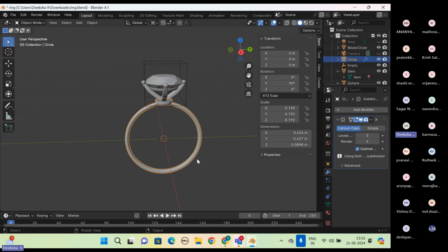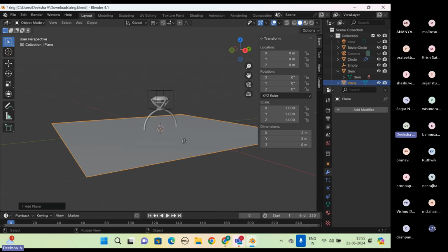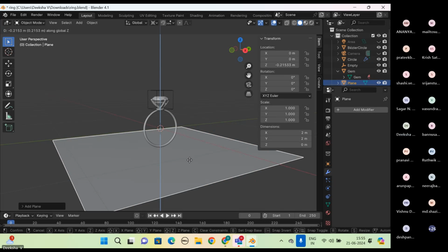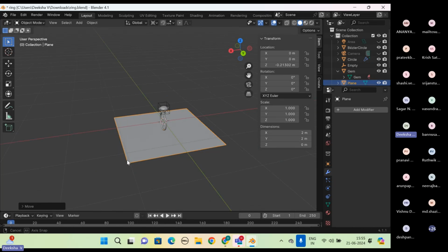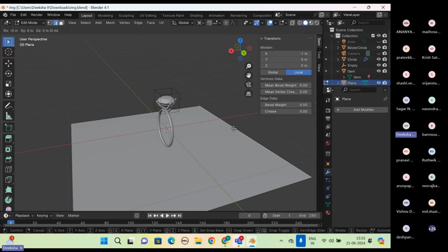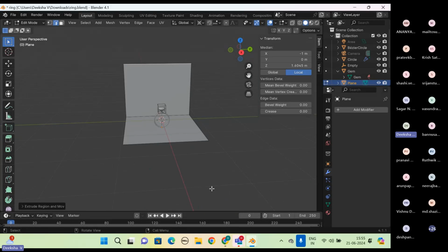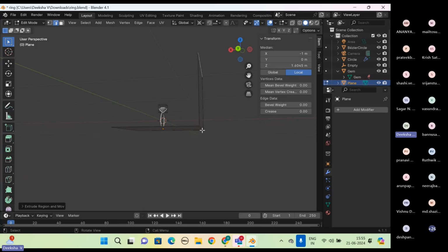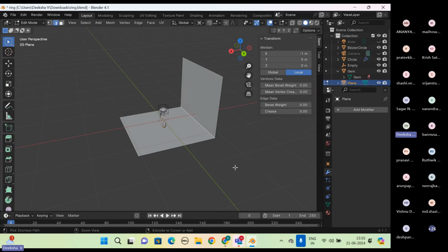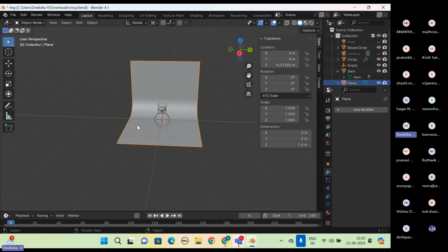To make an object look like this, now we'll have to add color. For that we'll need a background. So we'll add a plane. So Shift A, mesh plane, move the plane down a little, about here. Then go to your edit mode, go to edge select mode and extrude this top part a little. So E and Z, up to this level. Then you can click on this and bevel it. So hit Control B, increase the bevels, something like this. So it should look something like this.